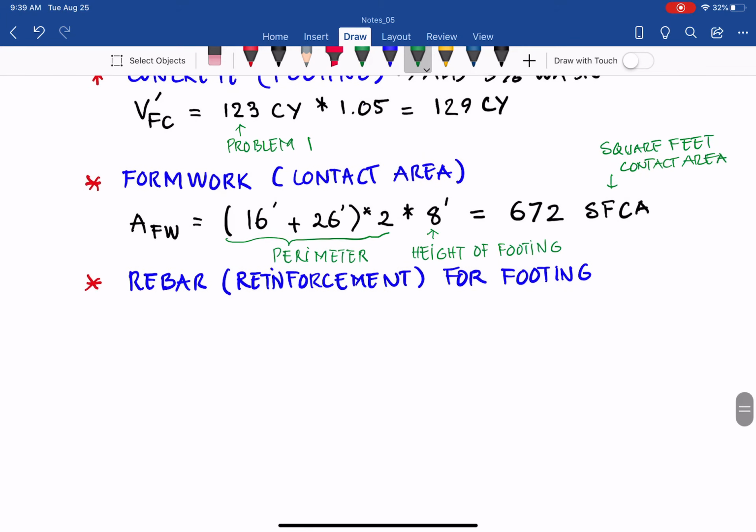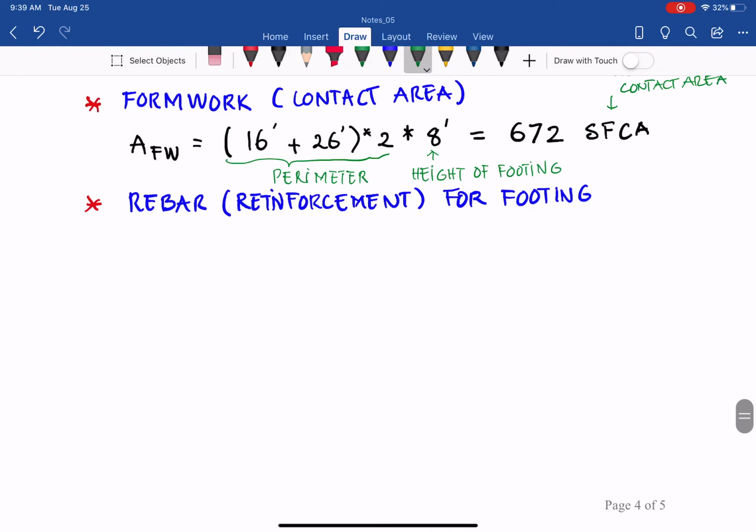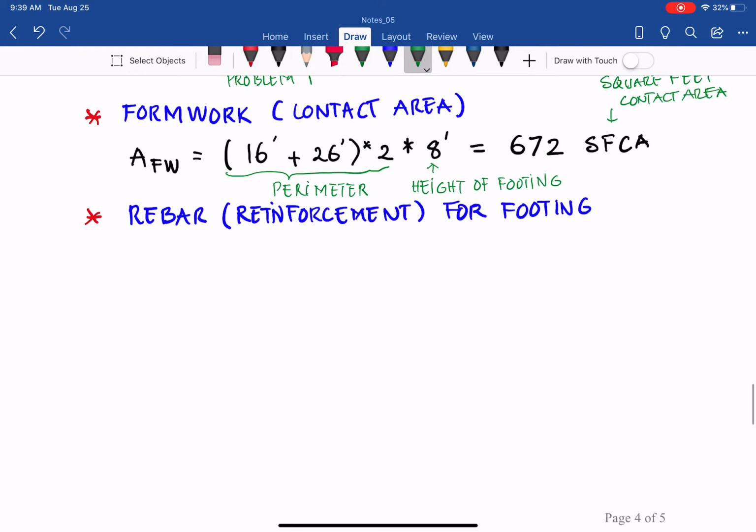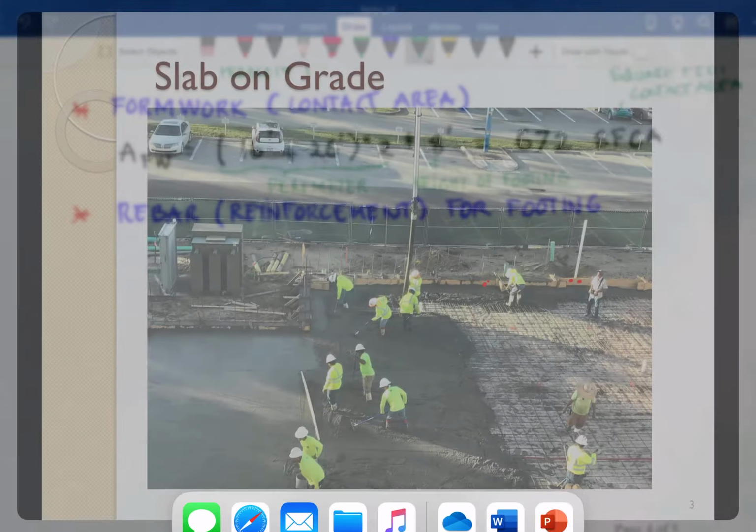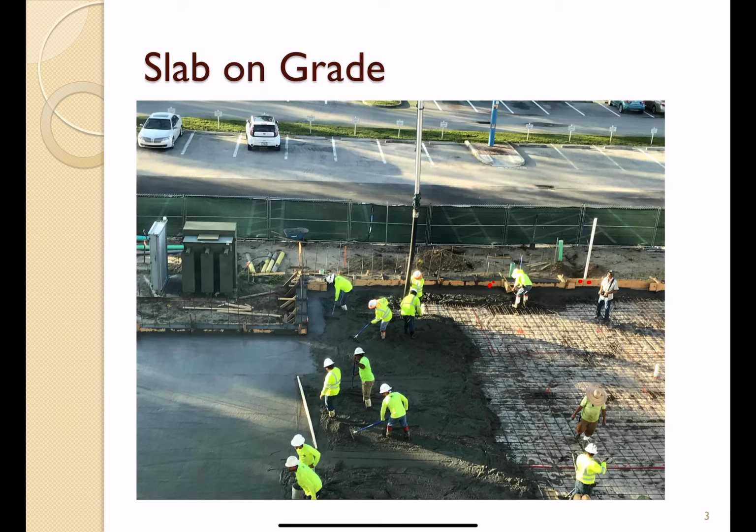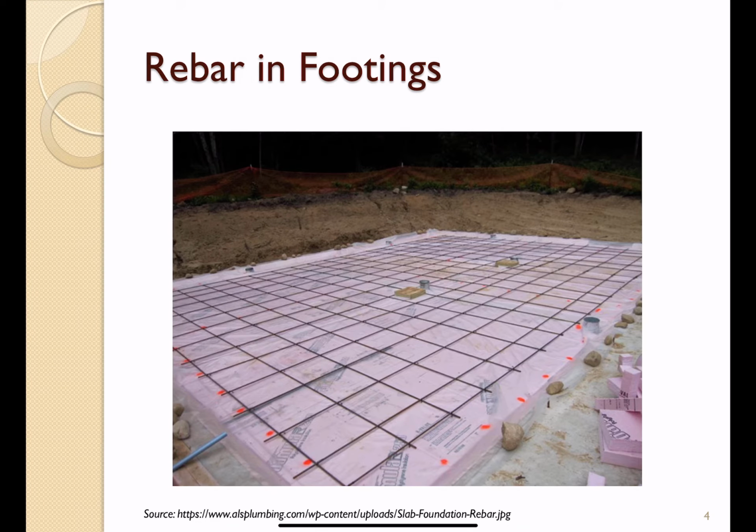So there are two, and if we put that down here, we can determine the length, and then we can determine the weight. First, we need to find out the length. Looking at the typical setup for the rebar, to find the total length we need the length for one side, count how many of them there are, and multiply the linear feet for one by how many.